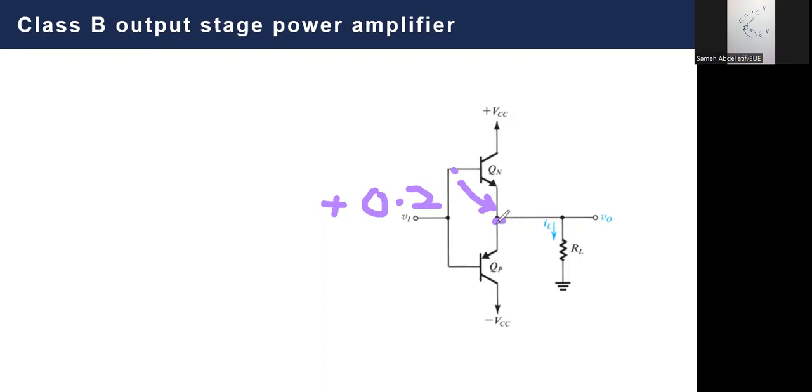On the other hand, this voltage equals 0, so it's still ground. And this is still 0.2. Here, the voltage of the base is greater than the voltage of the emitter, which is against the operation of this transistor. Because in order to make QP work, or turn it on, you have to have the emitter voltage greater than the base voltage. However, in this case, the emitter voltage is 0 and the base voltage is 0.2. So it's totally off. So that's the first case.